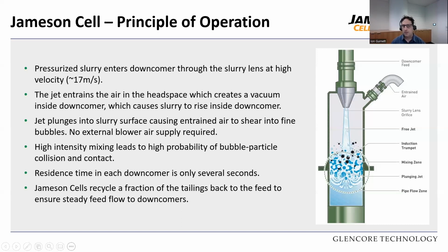Once it leaves the downcomer, your concentrate will float and go over the launder, while your tails will have a small portion sent back to basically ensure steady feed flow to the downcomers. By having the steady feed flow, you know performance is always going to be right, exact, and it's always going to behave in a good manner.